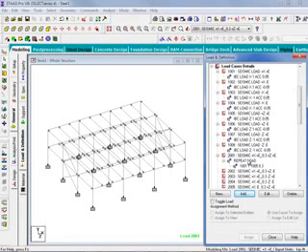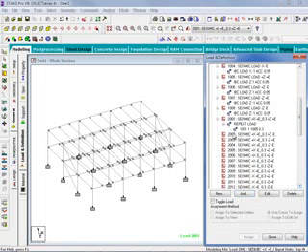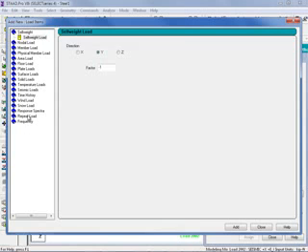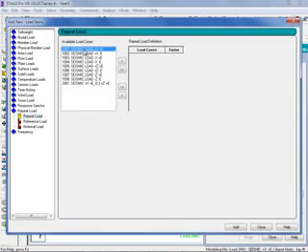I would then continue this process for the rest of them, and let's go ahead and take a look at the first 4. What I would do then is highlight my next seismic load case and click the Add button, and then I'm going to repeat this process. I'm going to take my 1001 series load case, but instead of the 1005, let me take the next one in the z direction. And I'm going to do this for each of the loads in the z direction. I'm going to click on my single right arrow and set the factor appropriately for that z seismic load case.